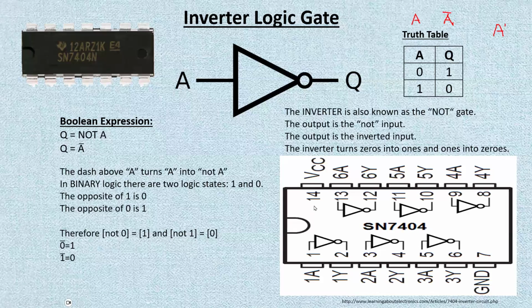Okay. And if you want to see some of the TTL logic, the 74 series, so that's a TTL, you will probably end up doing certain exercises if you haven't already. The inverter chip is, well, forget the SN, there's some designations that mean certain things of certain type of a chip. 7404. TTL stands for transistor-transistor logic, so that means the circuitry inside that chip is made out of transistors.